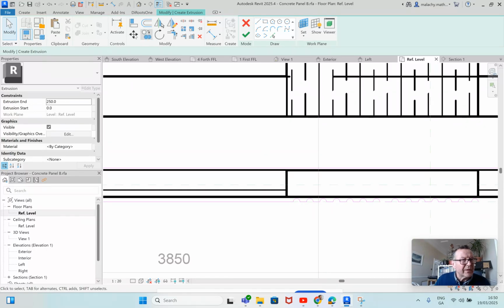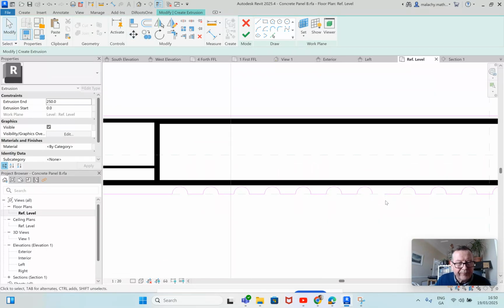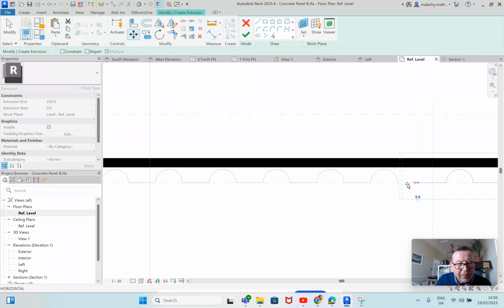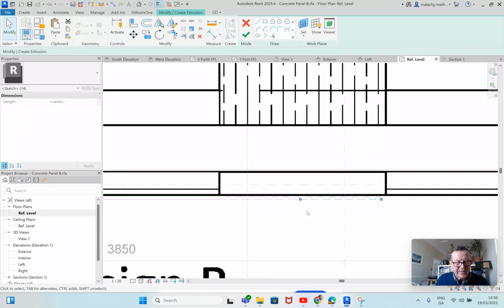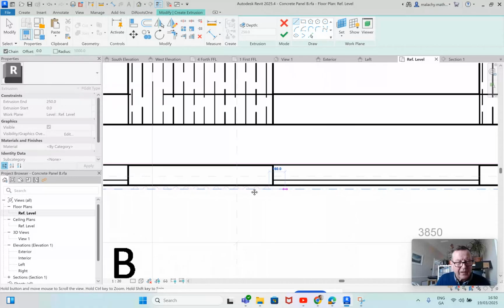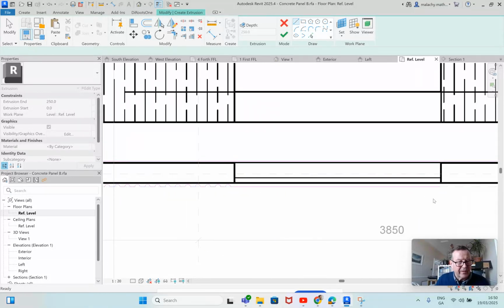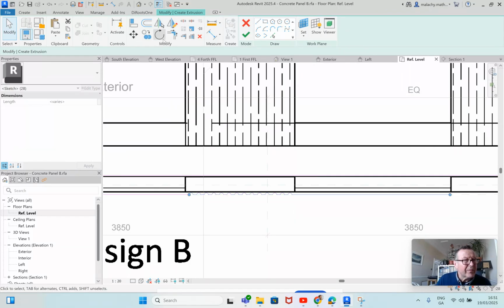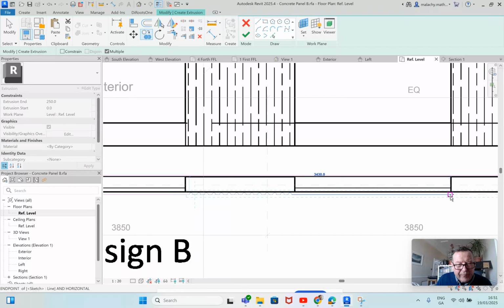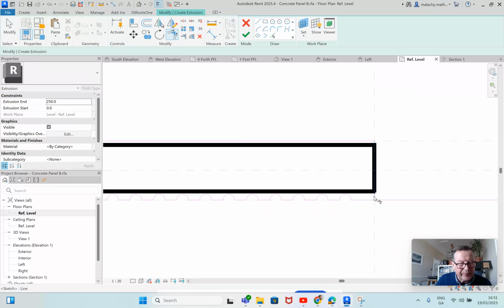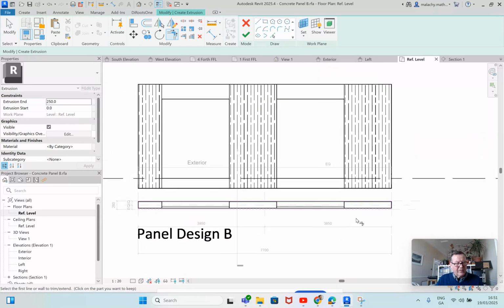Move these ones, sorry, not copy, move. Select, move into there. Now all of these, you have to be careful because all of these do have to join. Now I'm back into this one as far as here, and then we'll do that again. We will select all of those and go copy. Okay, and then we'll just fillet the end one here. Right, okay, so I've got roughly that done.